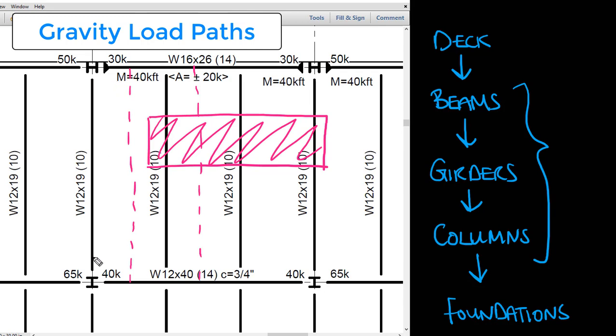And so if we look at this beam here, the next adjacent beam is this one here on this side, and this one on this side. And so its area of influence looks like this. And we can see that in fact there is some load that falls into that area of influence. Area of influence is also important to know because it is how we calculate live load reduction. And live load reduction is something that I have seen tested for on the ARE.